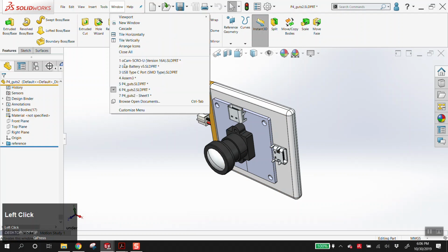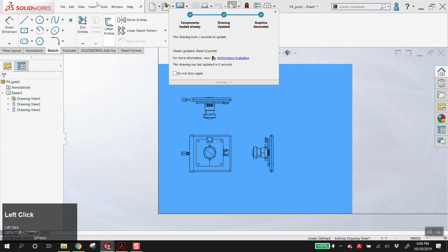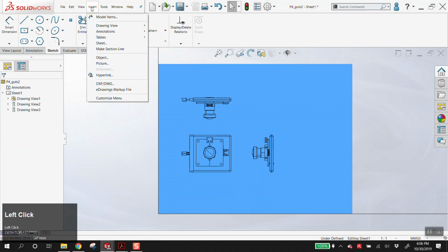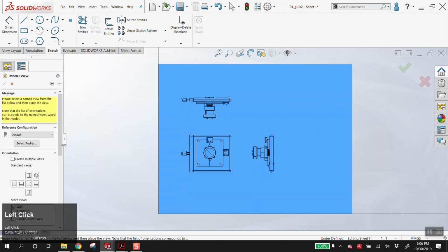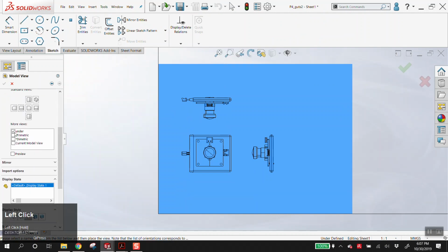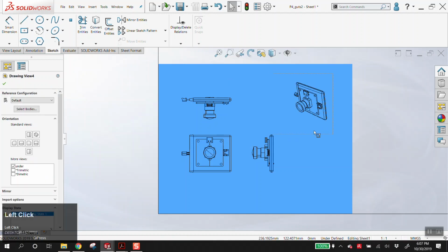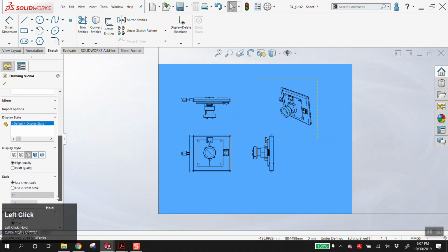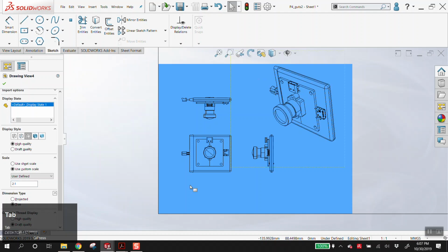The other nice thing is, if I go back to my drawing sheet here, I can say insert drawing view, model, get the CAD guts, and now if I scroll down here, under is an option in my views. I can drop this in here. This is a very quick way to make a perspective drawing. And now I have a sketch underlay. Again, hopefully this is useful for other classes. You can change the size, if you want to make it bigger.